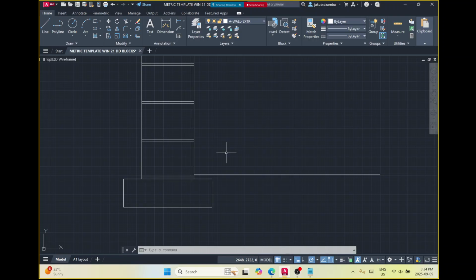Yeah, click the line. And now, I should have done it. To get matching marks, just use the grab. Escape twice, and now select the line with your mouse, and we'll use the blue grips to stretch it. Perfect, you got it.